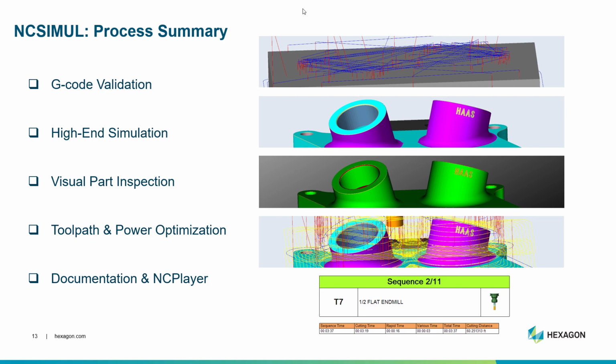And at that level, we can reduce air cutting. We can regulate the feeds in material for both chip thickness and chip flow, so volumetric engagement. And we can also utilize the power of the machine so that we don't overrun the spindle in any heavy machining locations. So that's an option as well.